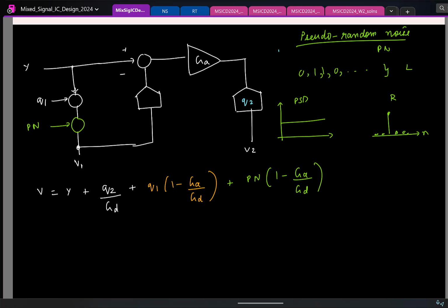And what operation do you typically do to find this? Let us say I have two signals x1, x2. I want to find how much of x2 is present in x1. It is basically trying to find the relation between the two signals. So what do you do for that? You take the signal, multiply it in time, and then you take the integration. That's basically called correlation. I mean, this shouldn't be surprising, right?